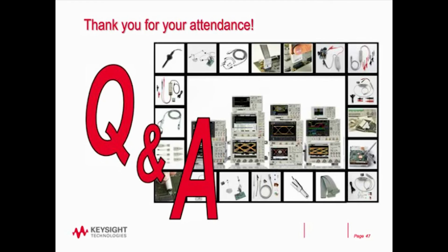Do you know which scopes offer WaveGen? All of the InfiniiVision X series, so the 2000X, 3000X, 4000X, and 6000X. The 4000 and 6000X offer 2 output channels and also double the output drive capability. Although for a PSRR measurement, you don't need high output drive. You're typically disturbing with a very low output signal.